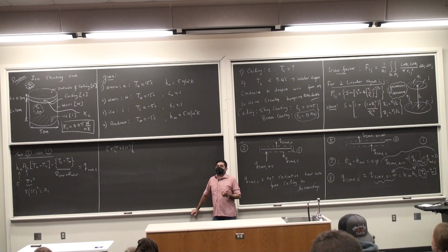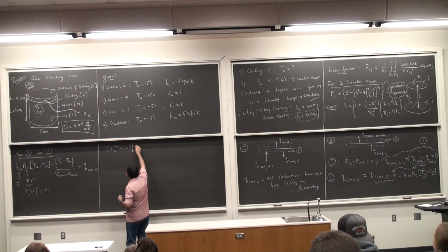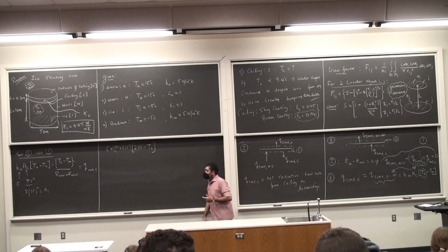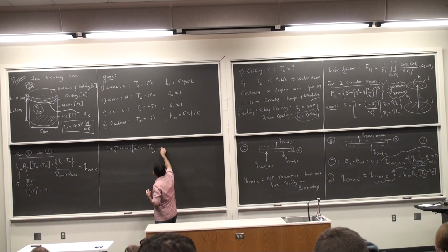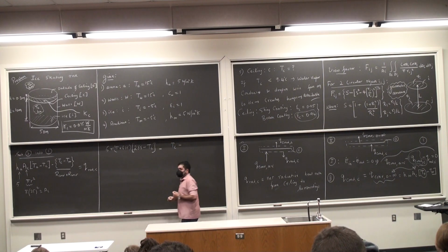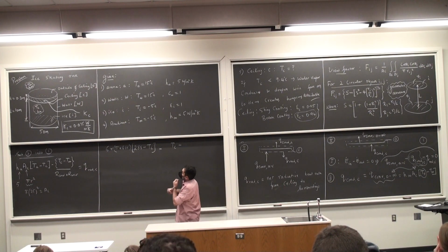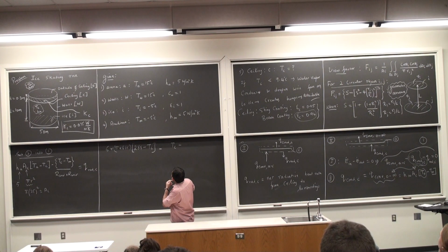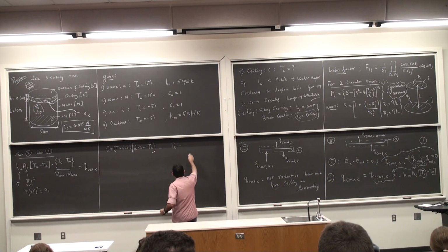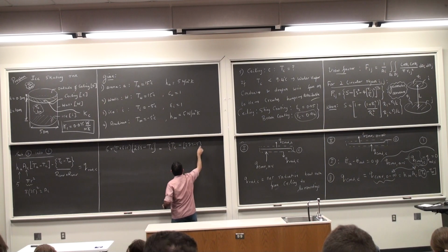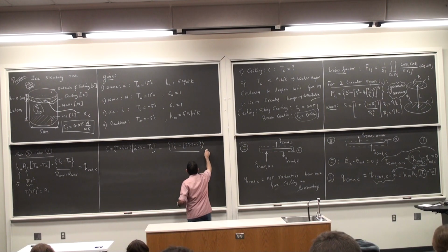You do not want to write it as 15 degrees. 15 plus 273. When radiation is there, everything has to be in Kelvin. This is 288 minus Tc. This is why I wanted to write it out. Minus Tc minus 273 plus T infinity was 5. So that's minus 5, I'm sorry. So that's 273 minus 5. All of this.